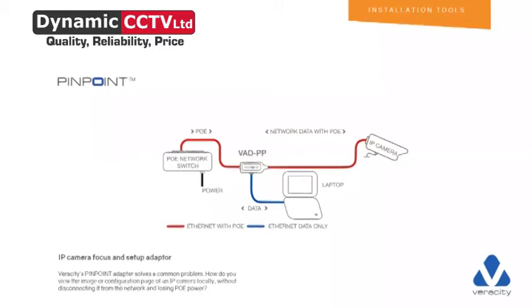So you've got PoE coming out from the switch out to your camera. You want to configure that camera and you want to do everything you possibly can, save you going back twice. Plug this into the Cat 5, 6, 7, whatever Cat version it is. That will power the device from the PoE from the switch, which will in turn power the camera. That plugs into your laptop, your iPad, or whatever you're using, and you can configure the camera with it.